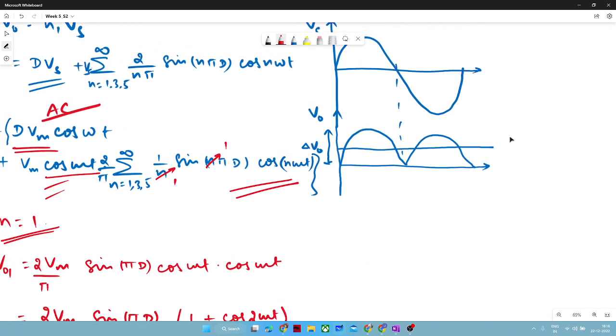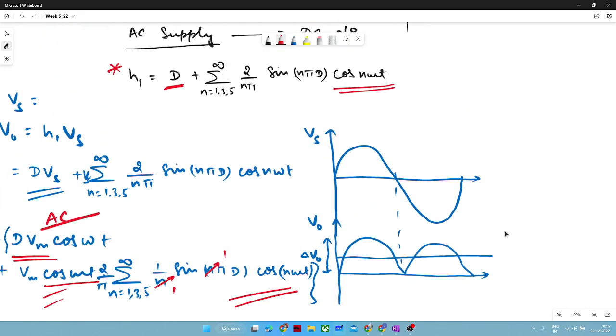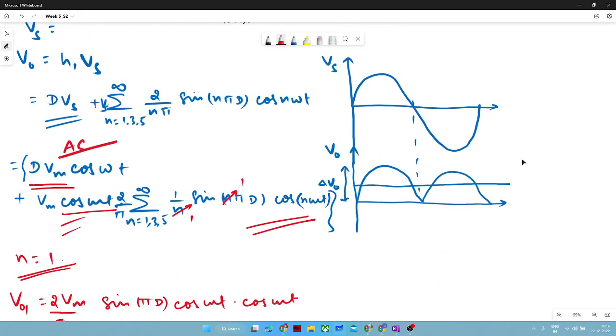Let us assume this is a half wave rectifier. So this is the kind of waveform you will achieve at output, and if you need, you can easily derive the average voltage of a half wave rectifier. Average is nothing but the area in your graph in one time period. So from 0 to 2 pi, however, the signal is there for pi only, right? Here this is pi, 2 pi.